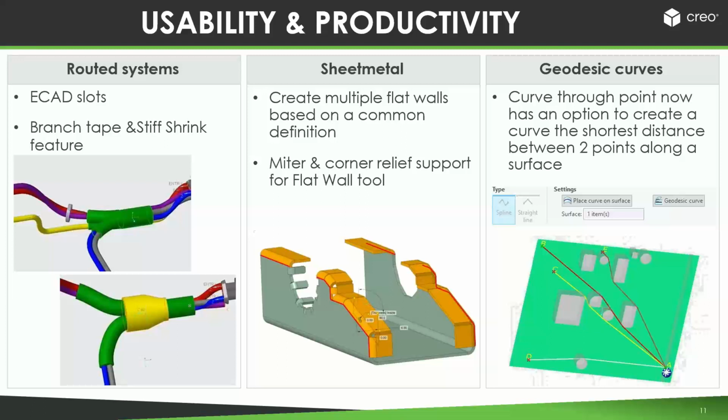And from there as well, we've expanded our ECAD support using the IDX format. That's the format that allows us to collaborate between ECAD tools and Creo. So we can collaborate by bringing in the PCB board outline and any holes that are in that board. Those are things we've been able to do. And now with Creo 8, we've added additional support for slots as well. So now we can bring in holes, those slots, and the board outline and be able to make our changes over on the ECAD side and on the MCAD side, and really collaborate between those users by leveraging that IDX format.